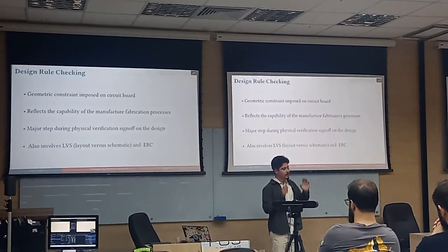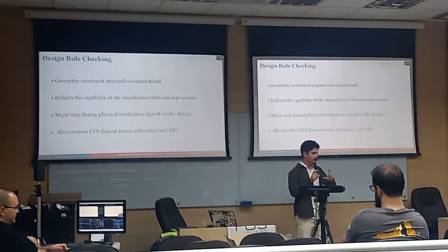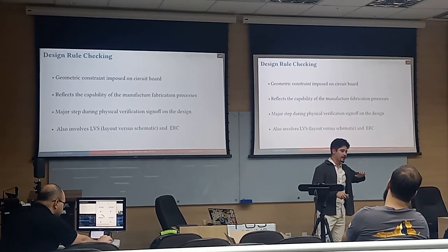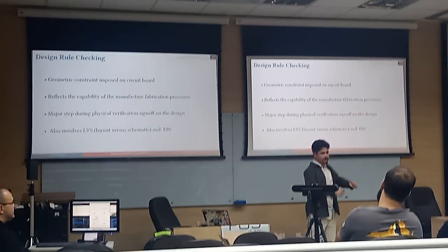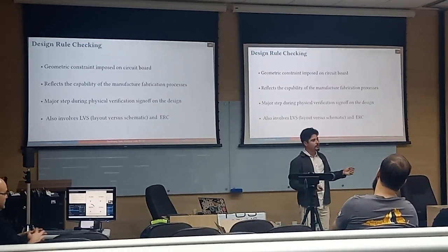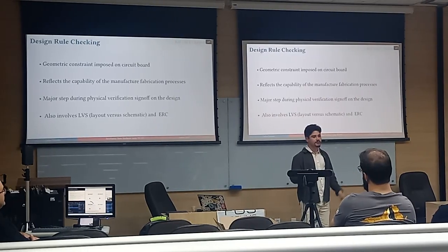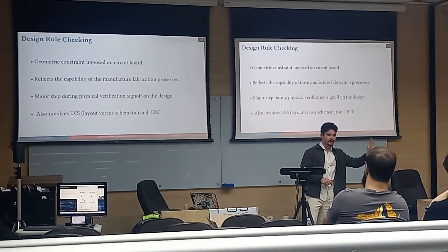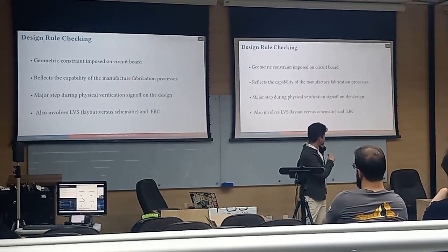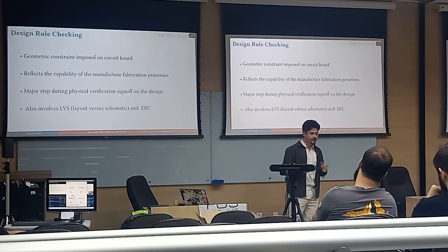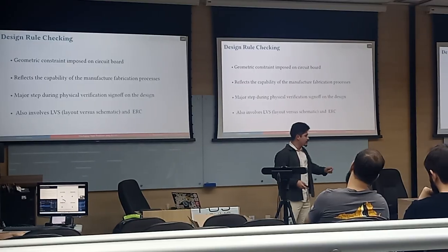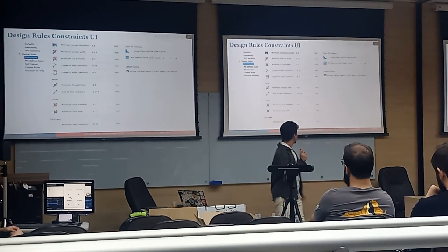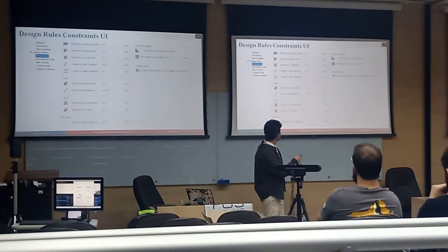The main point of the DRC is to check geometric constraints. It's not usual to check for parasitics and so on. But besides limitations on geometry, it also checks connectivity. For example, as I said, I want to connect this part and that part in the circuit, and I forgot for some reason. The DRC will warn me: you didn't connect this, are you sure it's correct?